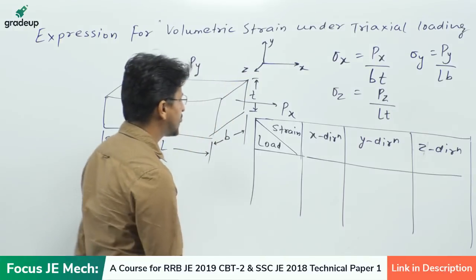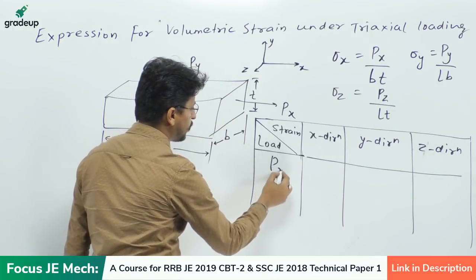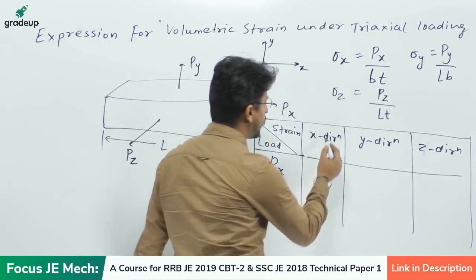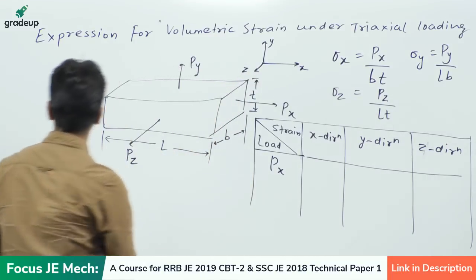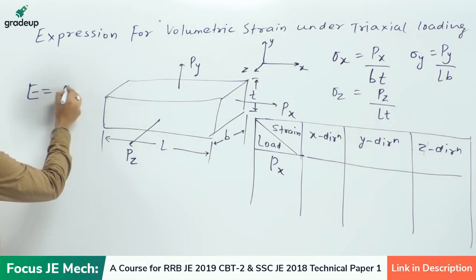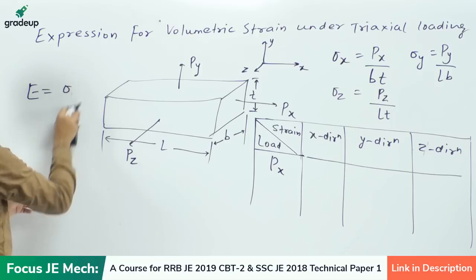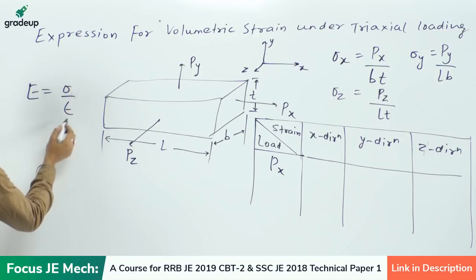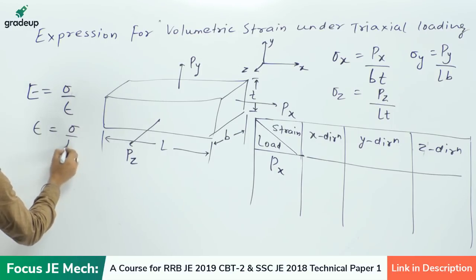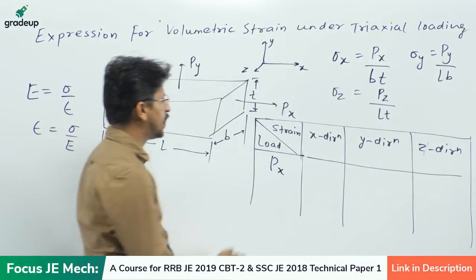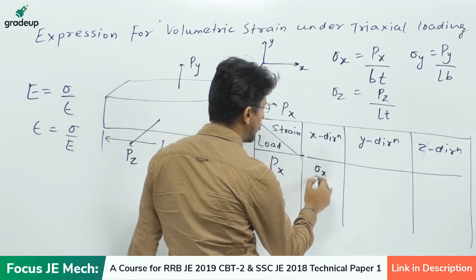Okay. In the x direction, due to this load Px, the strain will be how much? From the formula, strain is sigma over E. So in the x direction, due to the load Px, this will simply be sigma x over E.